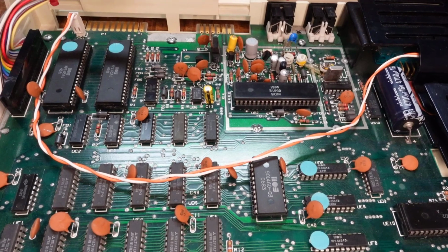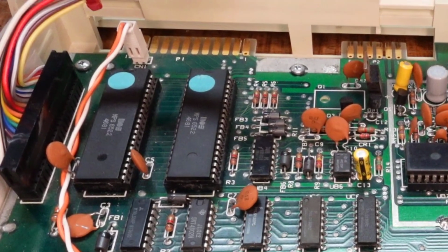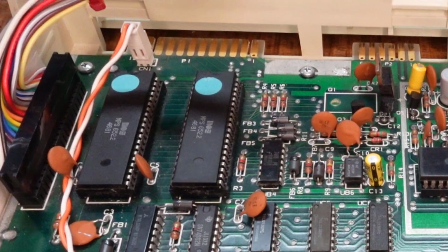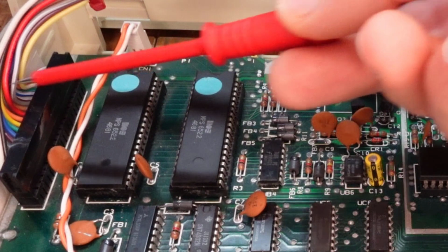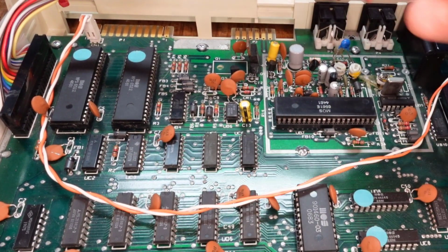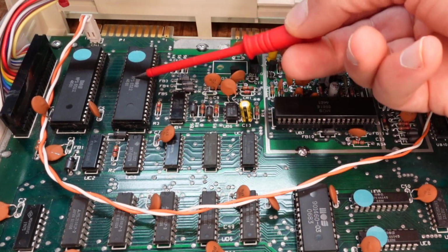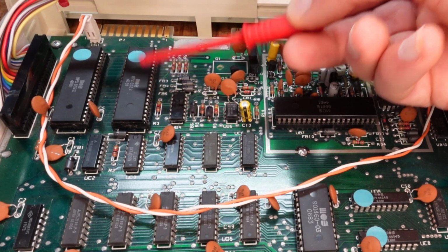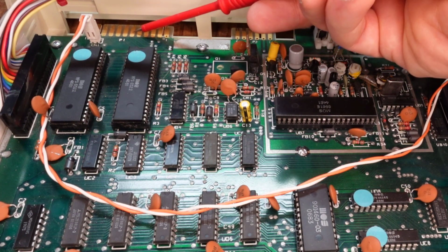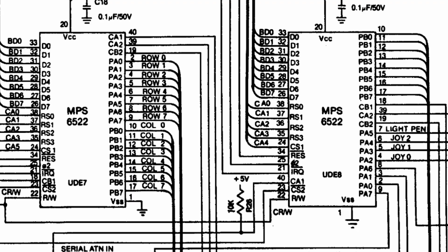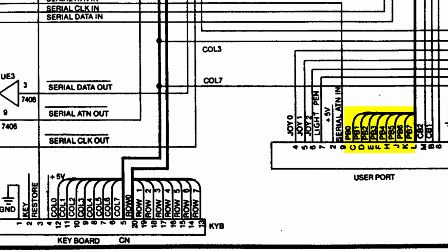The VIC-20 has 2 MOS 6522 I/O chips, also called Versatile Interface Adapter or VIA for short. The first one interfaces the keyboard and the serial floppy port. The second one is for the tape port, joystick, and also the user port. Here we have 8 out of the available 16 digital I/Os at our free disposition.